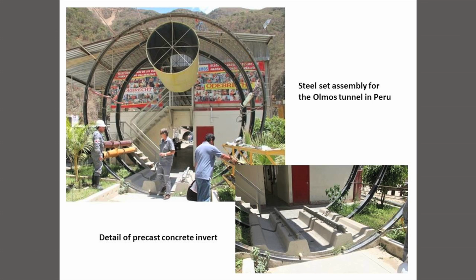And so as the tunnel progresses, those sets will take care of most of the minor popping and bursting that you saw in the video. Sometimes with a little bit of deformation of the sets or of the reinforcing above the sets, but safe enough for people to work in.